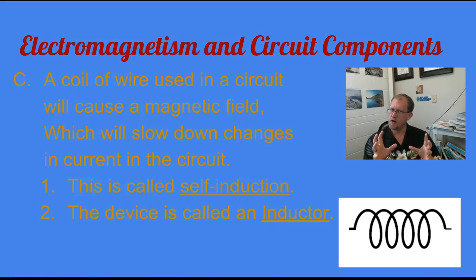Now we're going to take that same concept of resistance and magnetic interference, and we're going to apply it now to an electrical component. And these components are very small electromagnets. It's a wire that has been wrapped into a coil. It may or may not have a ferromagnetic core through it. And the current of the circuit causes a magnetic field which induces in that same wire a backwards current, just a little slight one. And so what it does is it kind of says, hey, whoa, let's not change.